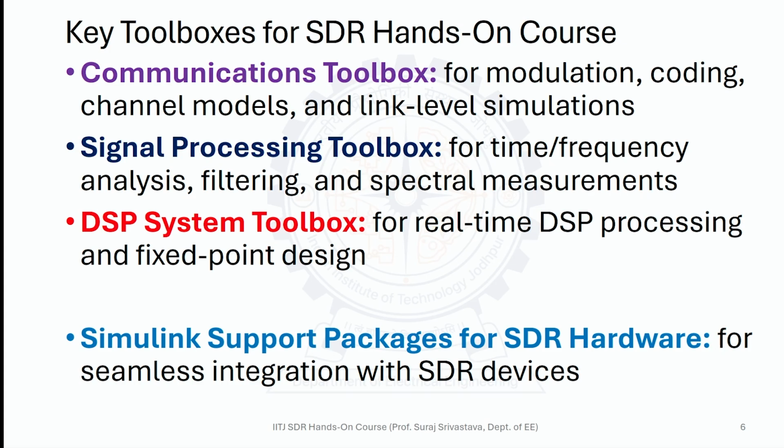Very frequently we will want to do time and frequency analysis, filtering and spectral measurements, so for that we will use the signal processing toolbox, and for real time DSP processing we will need the DSP systems toolbox. These toolboxes you have to install during the MATLAB Simulink installation, and in addition we will also require Simulink support packages for SDR hardware when you want to integrate your model with the SDR devices.